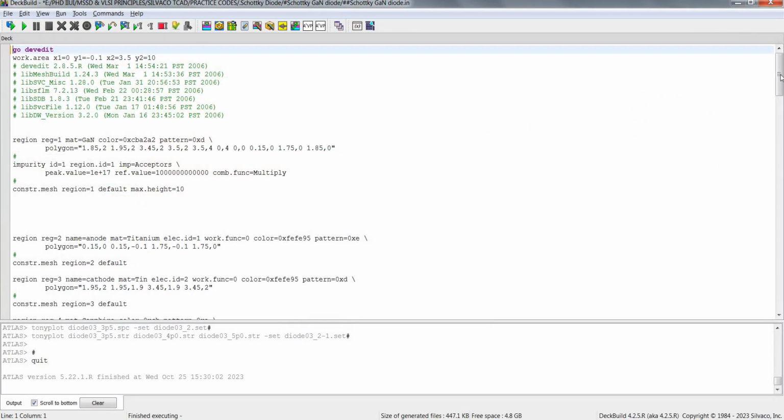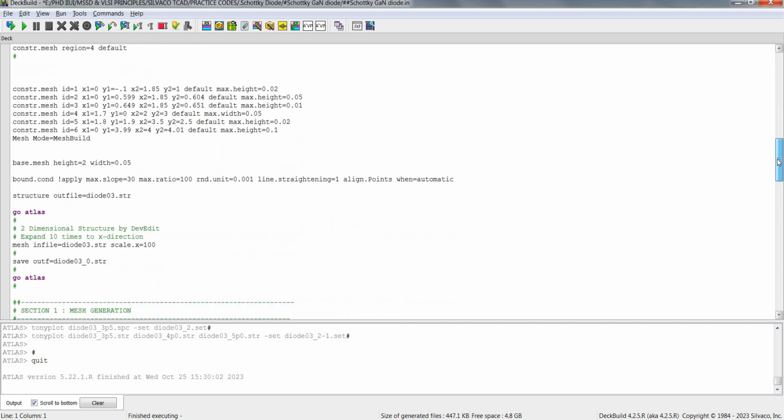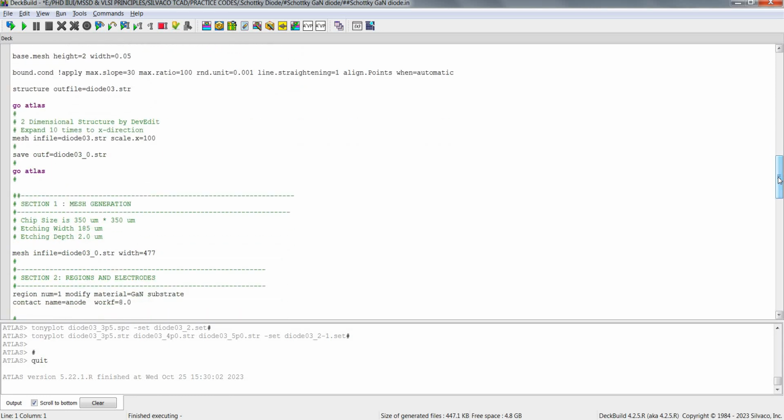And as I already told you, generally we don't have metals whose work functions are as high as 8 electron volts. So a good way to make good contacts to p-type gallium nitride is to dope the p-type gallium nitride material heavily and then apply metal contacts to it, resulting in tunneling behavior, and that would give you a good current flowing across the metal semiconductor junction.